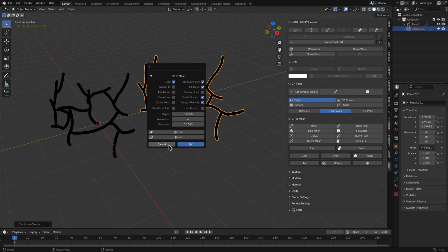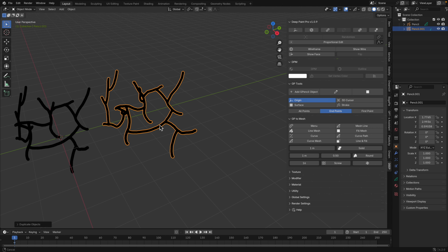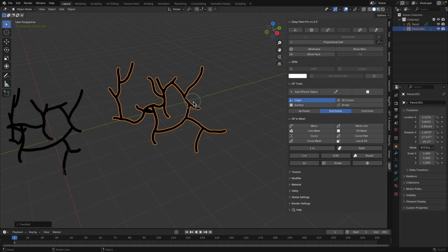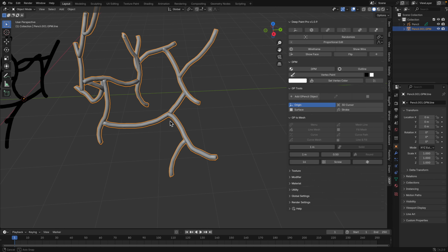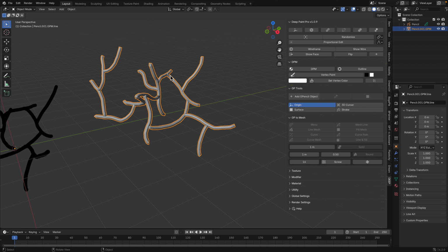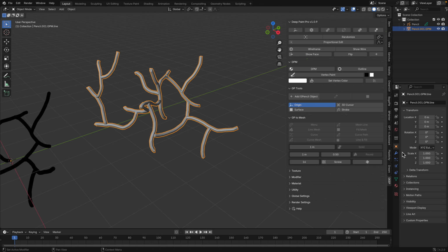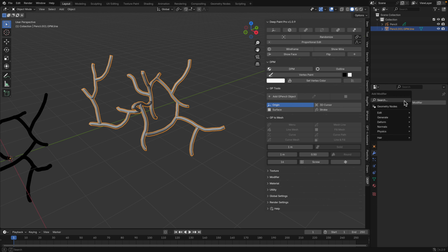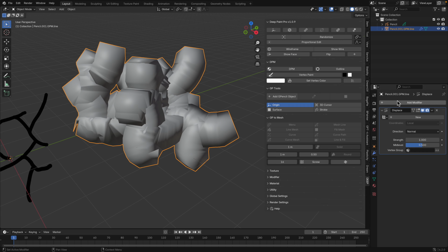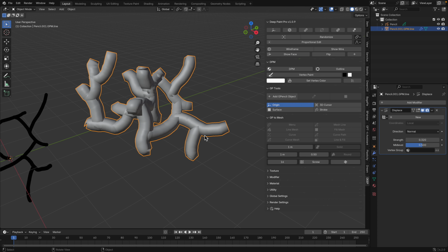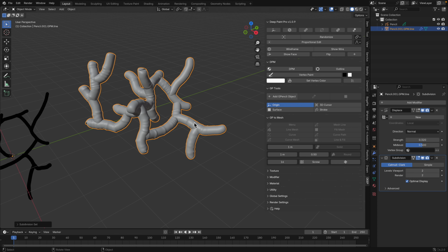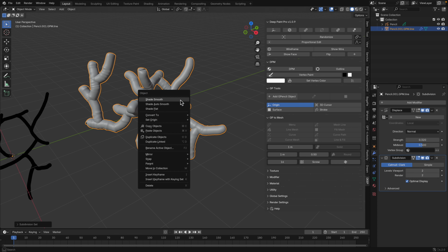It's got a lot of options there, but for now, this is the grease pencil that we have. I can go to E and then convert it into line mesh. Line mesh will turn it into some kind of solid 3D mesh object, right? And then if you really want to, you can displace, I like this feature, and then you can press Control 2 and smooth it. So that's one way to use this, I guess.